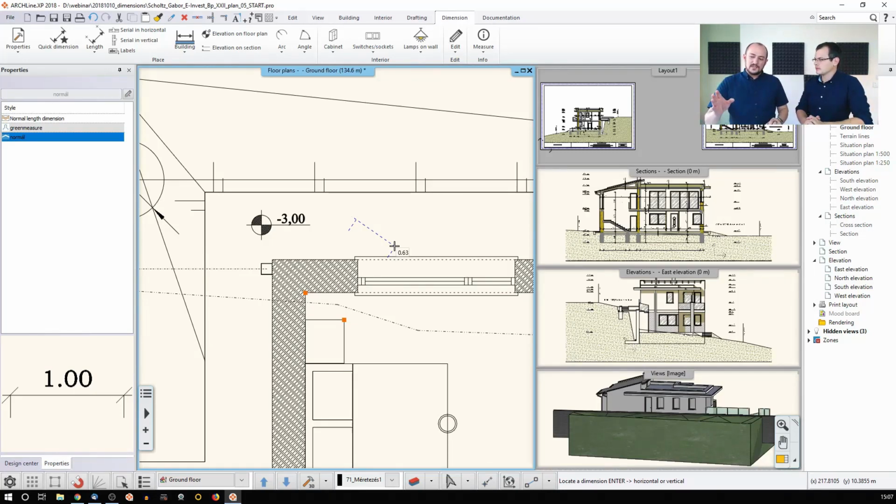But in this specific case, I'm not that happy with this because I would like to see either the vertical or the horizontal distance, but not the real distance. This tool allows you to switch between modes during runtime. The default mode is the real distance. The second mode, which I'm activating with the right click, is the horizontal component of this distance.